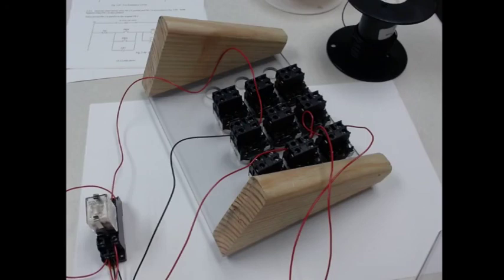Basically, we could add more contacts than we do at the bottom of page 34 in parallel for the start, and more in series to the left for the stop. Now you say, well, where does this come in handy? Well, I can think of a million cases where you're going to have a memory circuit, where you say I want to turn on, and then something else comes along and turns it off. You don't want to have to hold your finger on that button the entire time. So basically, it's a very simple way of having a memory circuit.